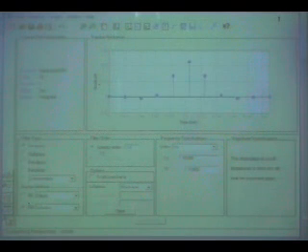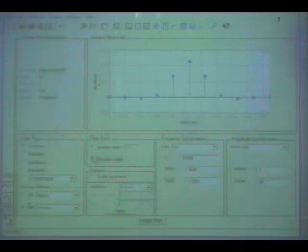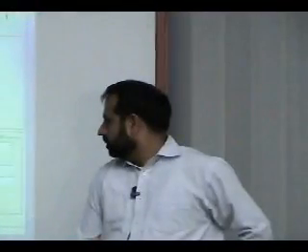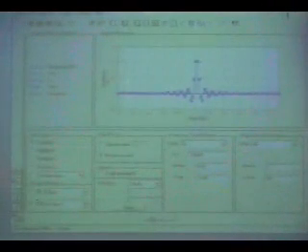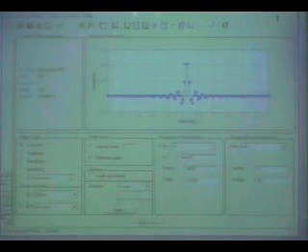So this is the impulse response. Our interest is in the impulse response. So if you specify a window, then you need to also give the order. If you say Kaiser, there you need not. Kaiser will give you the minimum order by using all those formulas. Though for every window people have come up with an empirical way of roughly figuring out the window length. So this is the Kaiser window.